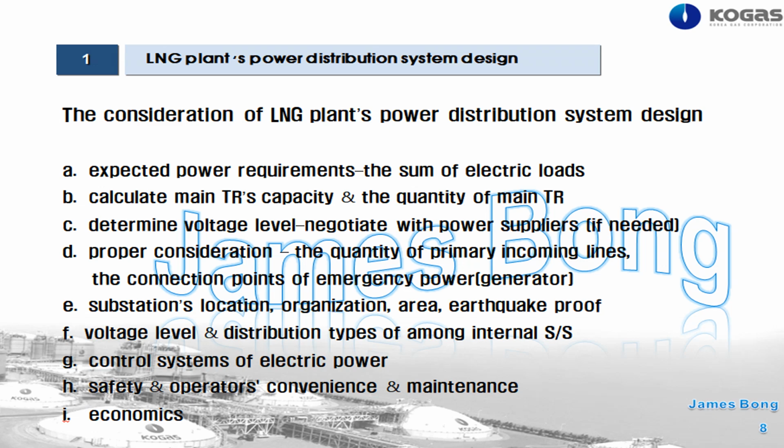Substation's location, cable route, earthquake proof, distribution types among internal substations, control systems of electric power and circuit breakers, whether using synchronous transfer systems, high-speed bus transfer or not. Absolutely, safety and operating and maintenance convenience and economics.